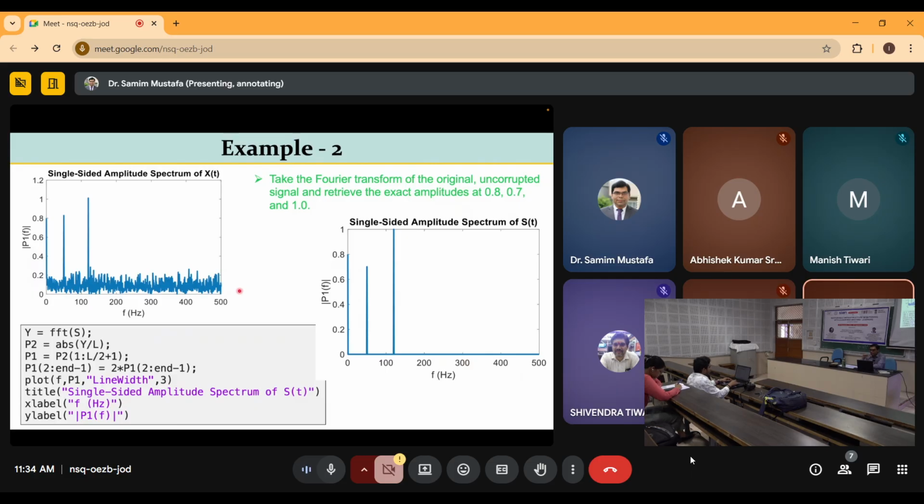There is some self noise coming from the sensor, and there is some ambient vibration happening on the bridge or any civil engineering infrastructure, right? If you assume those are white noise, meaning uncorrelated and independently distributed, they will look like this even if you do FFT.